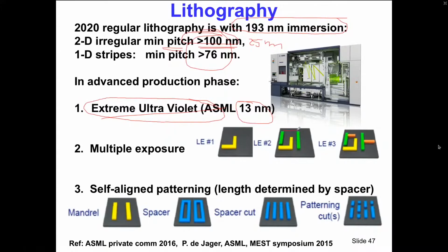So if these 2 green lines over here have a pitch of 100 nanometer, then the fact that I have before that inserted over here a first deposition of the same stuff, say polysilicon lines, then basically I can go down here to 50 nanometer, and if I do it with 3 times printing this material, I can basically go into say the 40 nanometer pitch area.